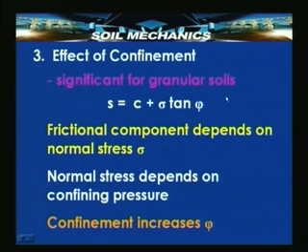Now, confinement is also again significant for granular soils. The frictional component depends upon the normal stress sigma, and the normal stress sigma depends upon the confining pressure, where sigma is the normal pressure on any potential plane of sliding. Therefore, confinement increases phi.